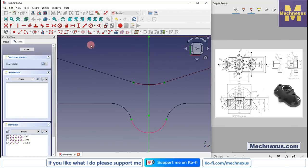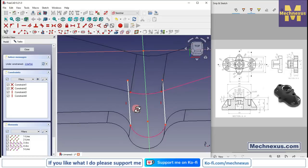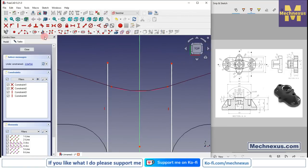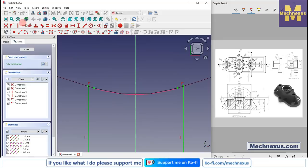Now here we will select the line tool, create two lines, and we will make it vertical, and this one also vertical, and click on the project geometry and move to the top view and click on trim it.